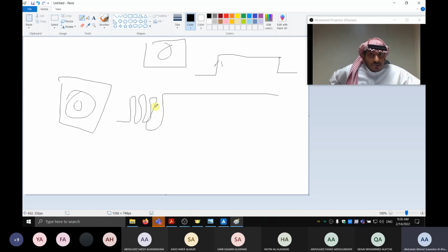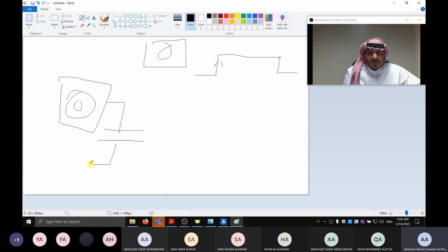So this bouncing can be fixed physically. It's not like you're doing a program or whatever. You can fix the bouncing issue. If we attach a capacitor in parallel with the button, when you press it, it will remove the bouncing. That's a physical fix. If you want to do any project in the future, if you have a button, you add a capacitor in parallel to it.